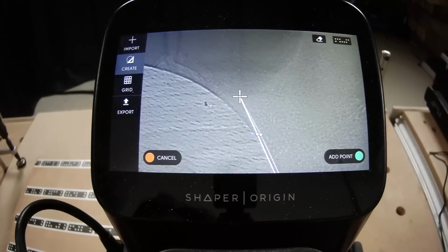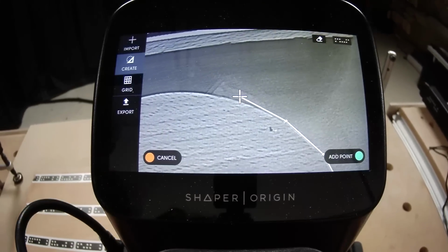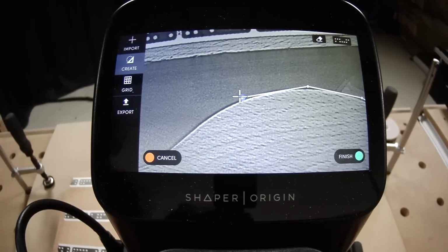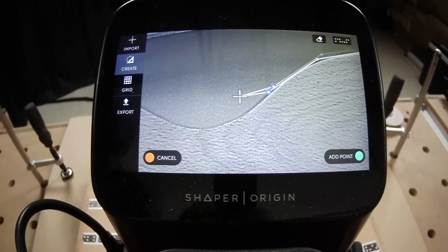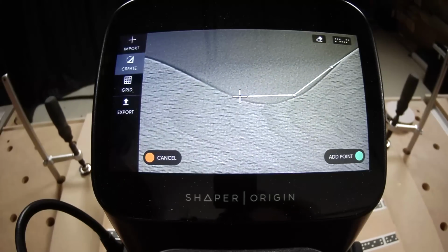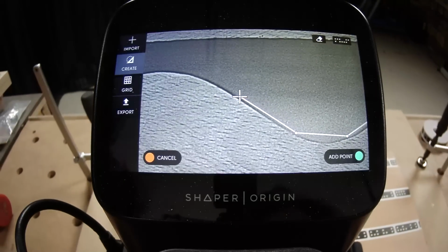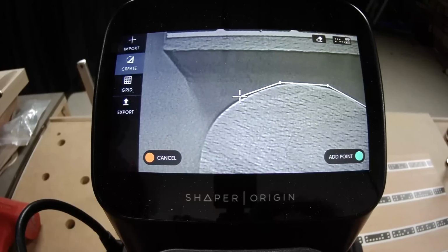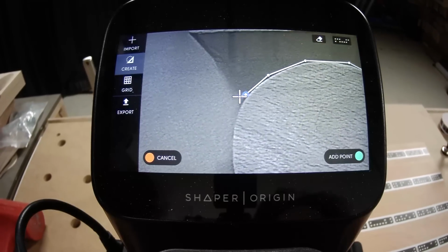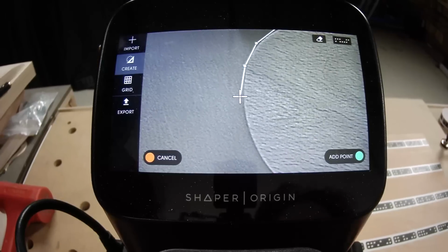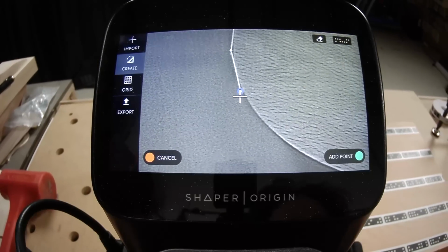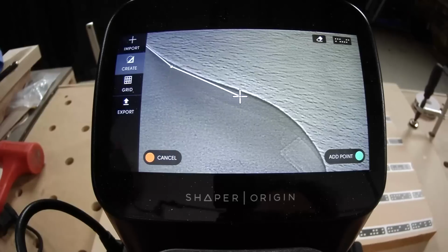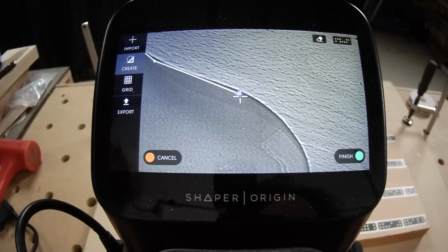It's giving us more of a guideline. And when we move this over into Studio, we know that we did this with a 4mm bit. So we can kind of imagine, all right, our true shape is 2 millimeters in on either side. Just a hair smaller than what we're seeing. I see. And what I'm seeing here is that when the curve is tight, maybe I want to do more points. Exactly. But when the curve is shallow, you can really space it out.